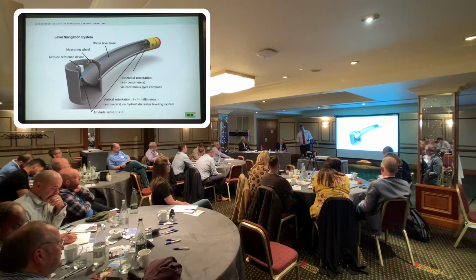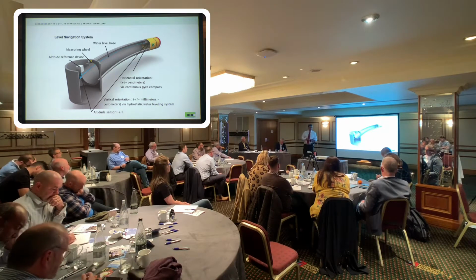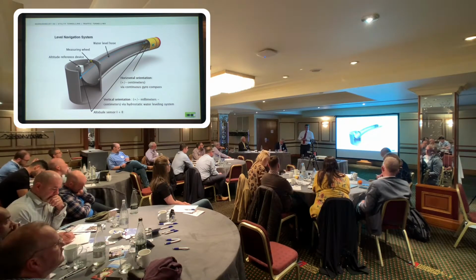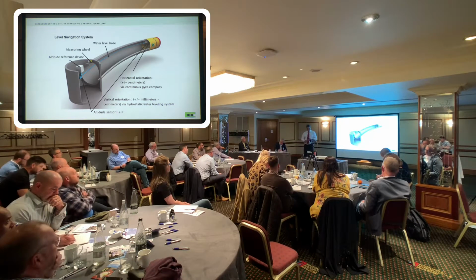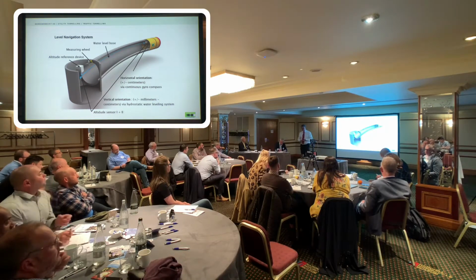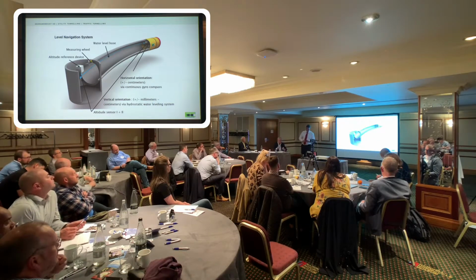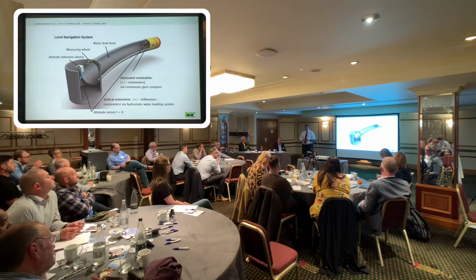Do not put it straight after the exit from a shaft. Give a tunnelling machine some time to run in a straight line. So it can get in the ground, you can get the loads bedded in, the jacking frame can get bedded in, and you're not trying to dissipate load very, very soon after the shaft bottom by inserting a curve. So the best curved pipe jacks will go several hundred metres or 100 metres in a straight line and then start curving in whichever direction.